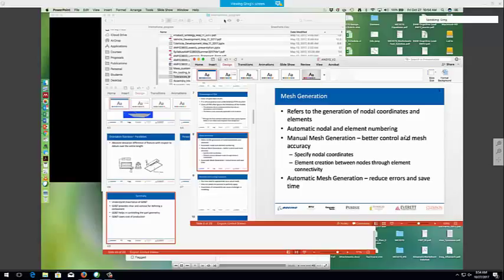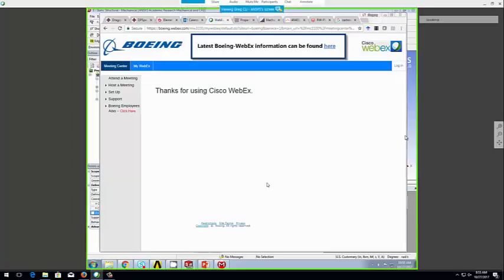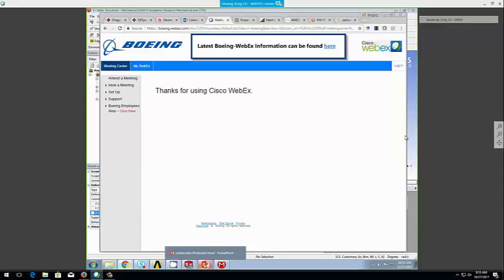I now want to bring in geometry. Okay, I'm going to right-click on geometry and import some geometry. Now, we at Clemson did not buy any translators, so it doesn't take native files very well. Tyler Stapleton talked about all of the different types of formats that 3D Experience has. I tend to be a user of STEP, so I'm going to browse for a STEP file. It should be noted that I created this STEP file from SolidWorks in this case. You could create it from any number of CAD applications, but we would encourage you to use 3D Experience.